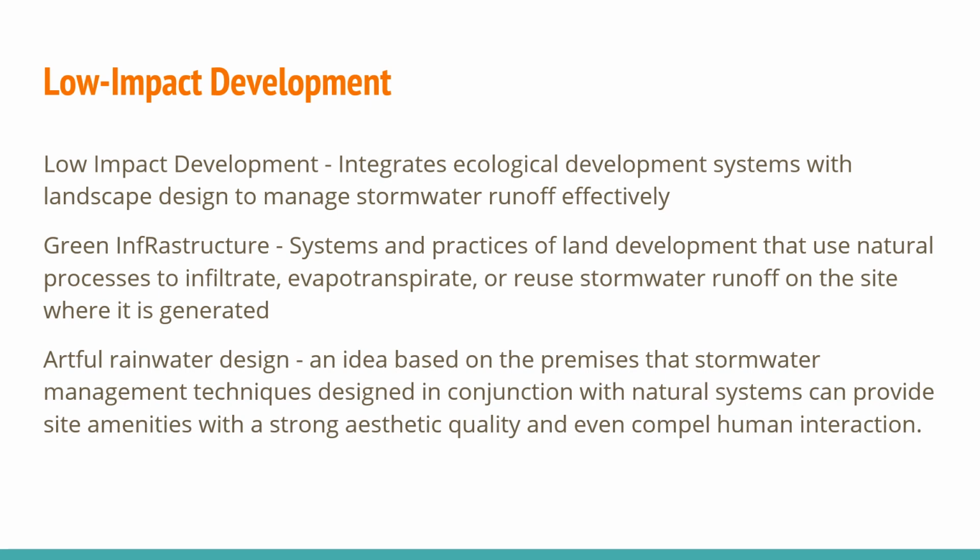We call this low impact development, which integrates the ecological development systems with landscape design to manage stormwater runoff effectively. This creates green infrastructure, which are systems and practices of land development that use natural processes to infiltrate, evapotranspirate, or reuse stormwater runoff on the site where it's generated.